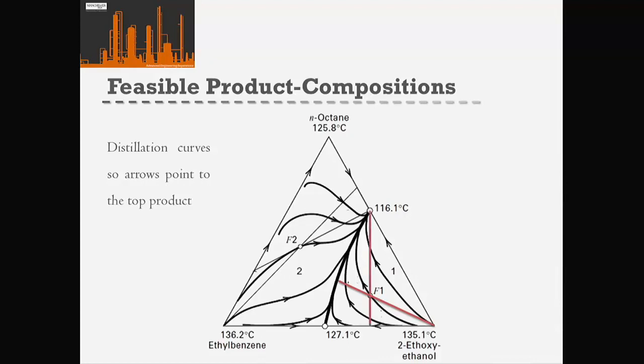We can also draw based on our extreme top product or distillate. And then here's our key residue curve. Again, we can think about what is our space above our residue curve to our extreme distillate, and what is our space above our residue curve and our extreme bottom product line. Again, we generate our two feasible product regions.